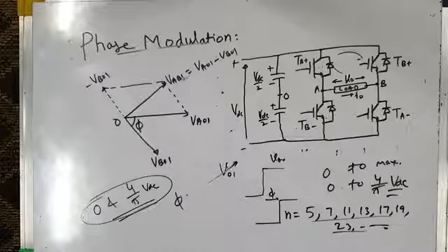Using the switching angle plane concept, we have tried to understand how we can control the inverter output voltage. We have developed the contours for controllable inverter output voltage, V1 contours, if you remember. We have also developed the contours for V5 equal to 0, that is 0 fifth harmonic voltage contours. We have also identified the 0 seventh harmonic voltage contours, that is V7 equal to 0 contours. Similarly, we can develop the contours for 0 11th harmonic voltage, 0 13th harmonic voltage, and so on.